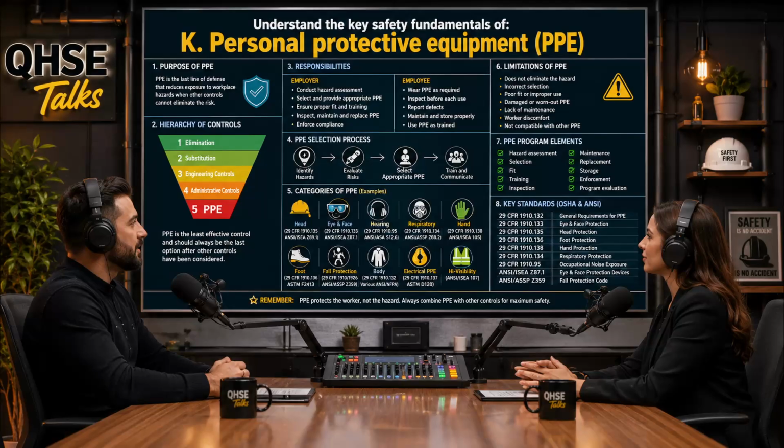Chainsaw chaps. Oh, chainsaw chaps are amazing. If a lumberjack is operating a chainsaw, the chain is spinning at roughly 50 to 60 feet per second. If that saw kicks back, a heavy pair of denim jeans offers zero resistance. The teeth will shred denim and sever the femoral artery in a fraction of a second. It's gruesome. So how does a piece of fabric stop a motorized blade?